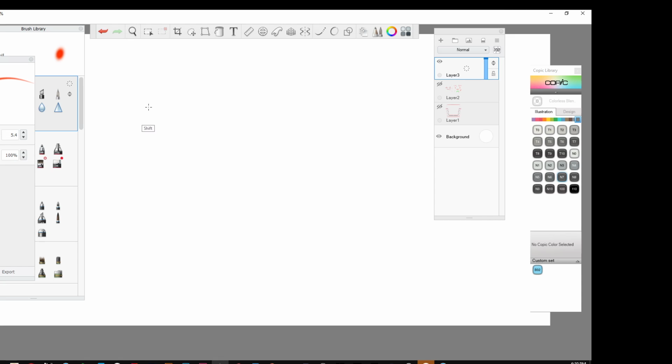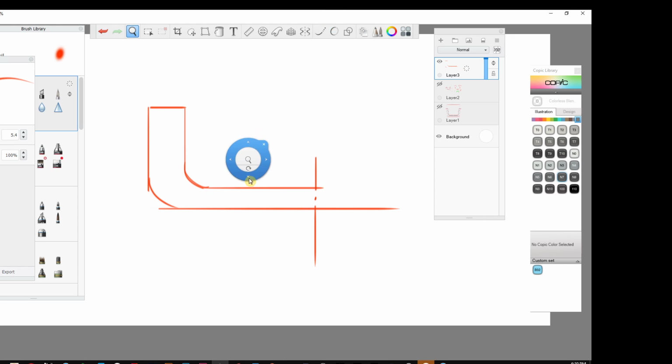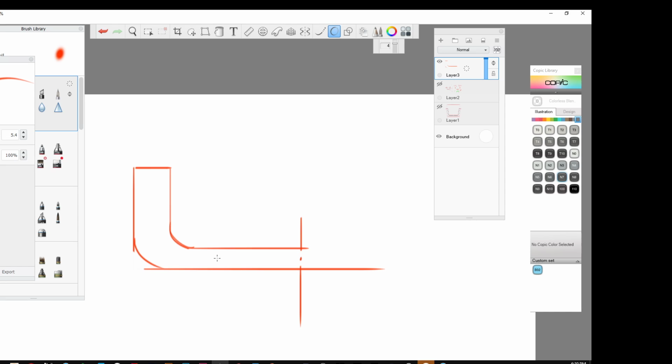So you've got this part, and then it comes this way, and then there's the interior. We'll only draw half. So what we know is that there's going to be two parts that come out, or two tools. We're going to have the top and the bottom that are going to build the cavity. So this is the internal. So we're going to have two parts coming in two different directions for this part, and for almost all parts.